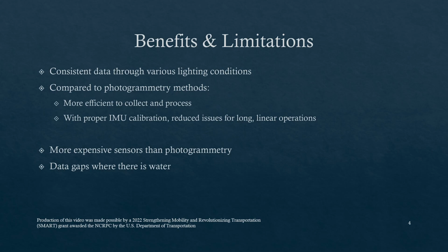Some of the benefits and limitations: the biggest thing with drone-based LiDAR is you're going to get consistent data through various lighting conditions. This is opposed to the photogrammetry method, where you're reliant on a well-illuminated subject area. LiDAR doesn't need that. Compared to photogrammetry methods, it's also much more efficient to collect and process elevation information with LiDAR.